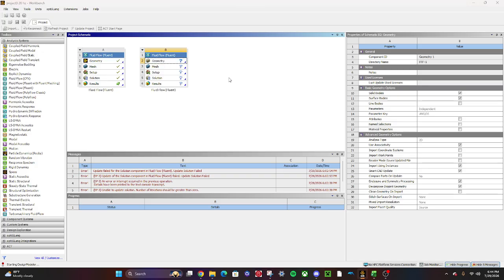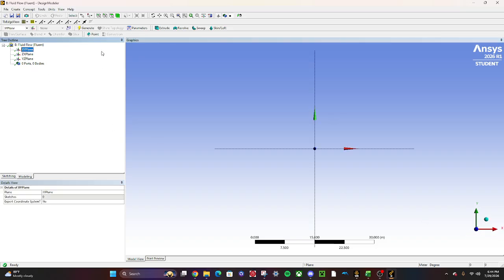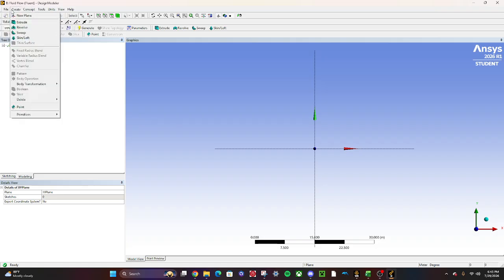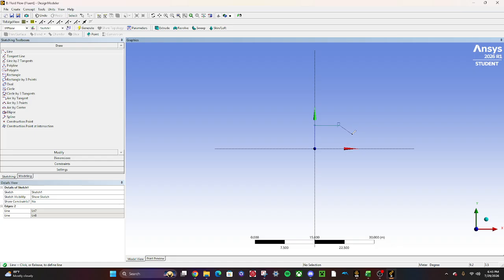This one is going to be a little more complicated than the past couple because it's going to be more of a shape with the chambers for the wind tunnel rather than just one constant, like either a rectangle or a simple slope. So we're going to go to the XY plane, go to sketching, create a line, and just start drawing out the basic shape of what this should look like. It should be something horizontal here, line down, line across horizontally, then finally a line up like so. And then we're going to want to go to dimensions.